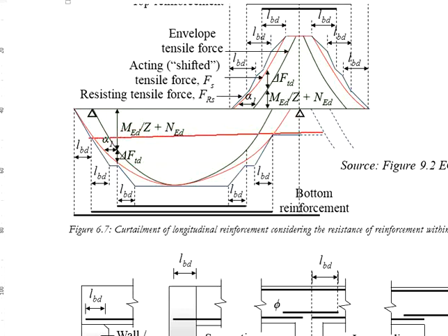You may find the intersections of the resistance given by the first group of the reinforcement. Start working out the development of the stress and then obtain the resistance areas of the reinforcement. Again, you have to check the angle of the anchorage length against the required. If the resistance angle is steeper, then you may start at the intersection point.